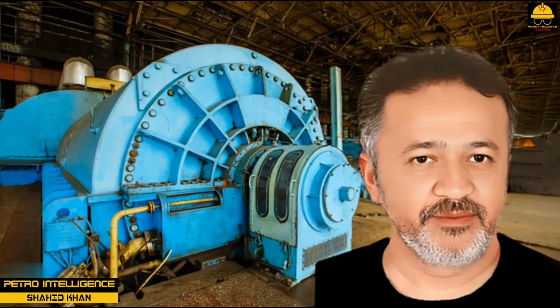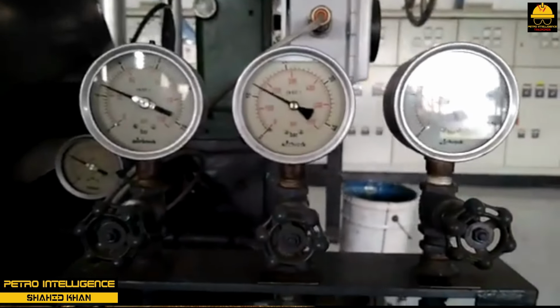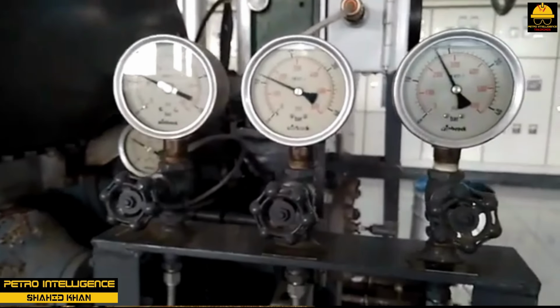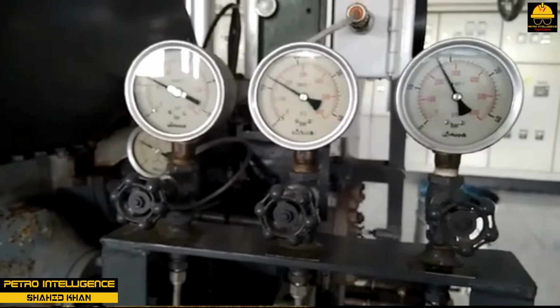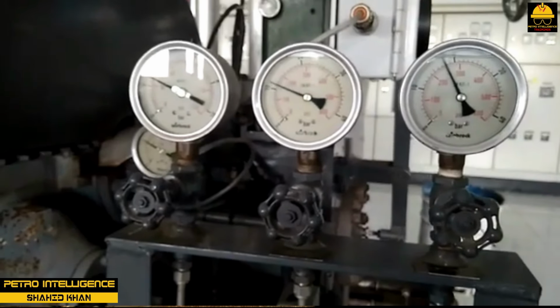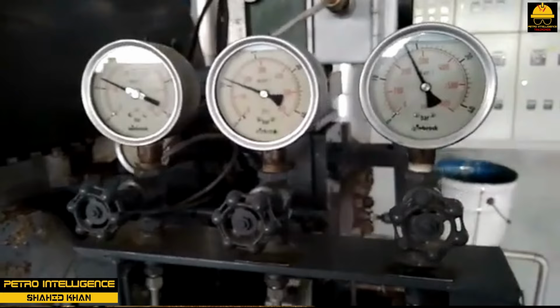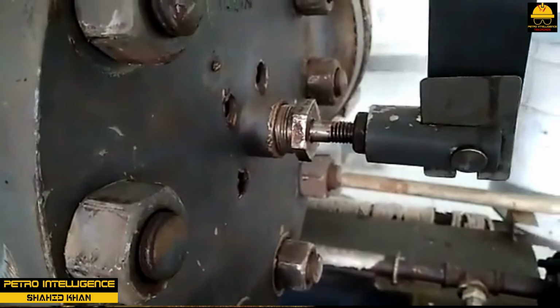Steam turbine problems. Steam turbines are susceptible to 2 types of problem: vibration and hunting. Vibration sensing equipment is used to monitor turbine performance. Probes are used by process technicians to check inboard and outboard radial and thrust bearings. Excessive vibration could indicate failing bearings or internal problems. There are 2 types of vibration: radial vibration and axial movement.